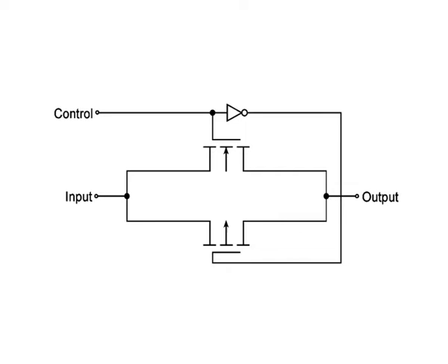In the case of an N channel MOSFET, if the source voltage is close to VDD, there is an increase in on resistance leading to an increased voltage drop across the switch. A similar phenomenon is observed when the source voltage of a P channel MOSFET is close to ground.